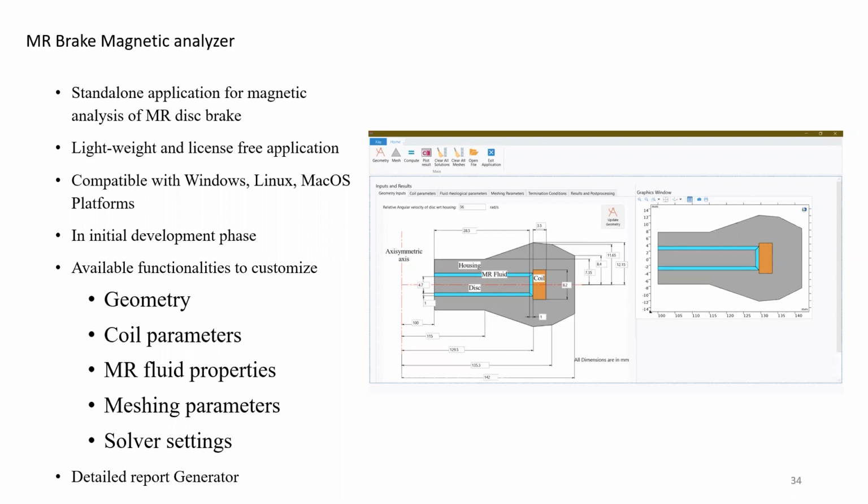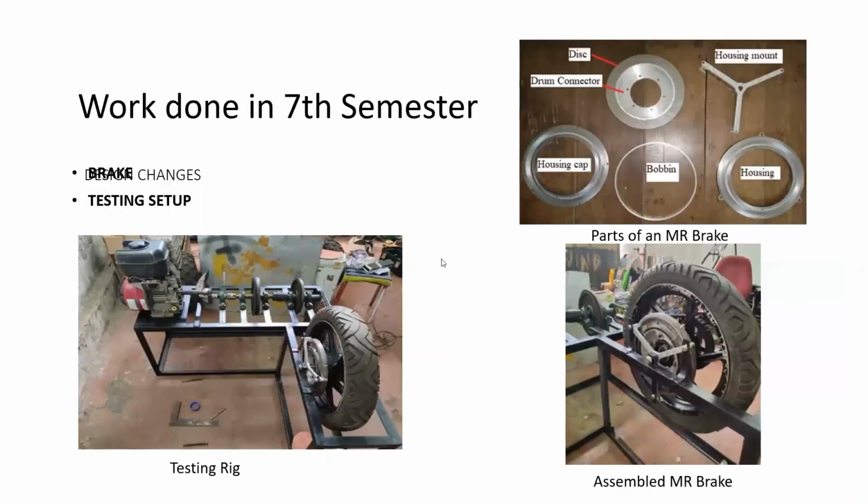After all this analysis and calculation, we have actually fabricated this at NIT Calicut. This is an IC engine connected to this flywheel, and then to the two-wheeler wheel, and this is the brake. When we designed, we designed it for 210 Newton meter. This much Newton meter is even good for a four-wheeler, because as I earlier informed you, audience, the Hero Honda requires hardly 15 Newton meter, whereas our simulation can actually generate 215 Newton meter.